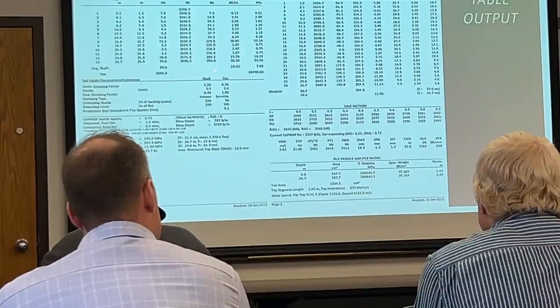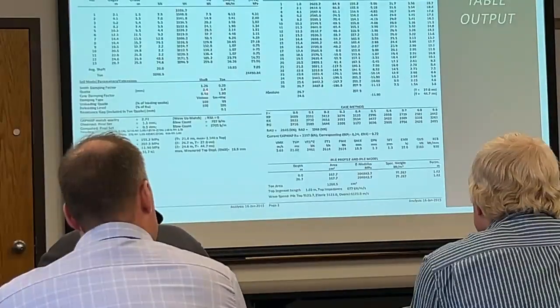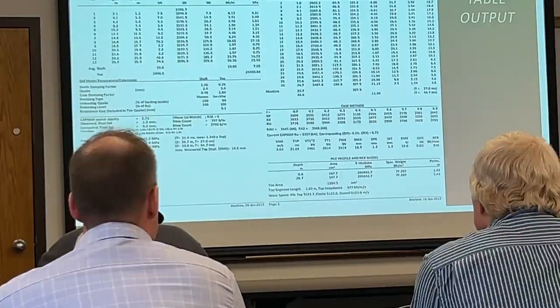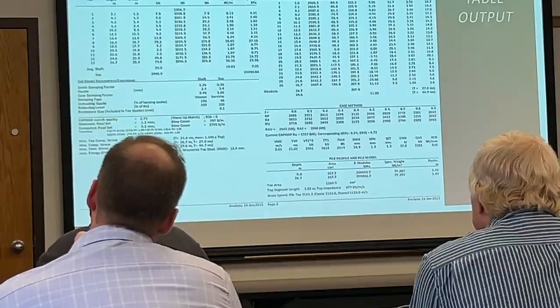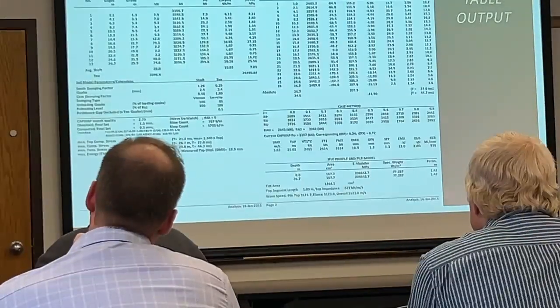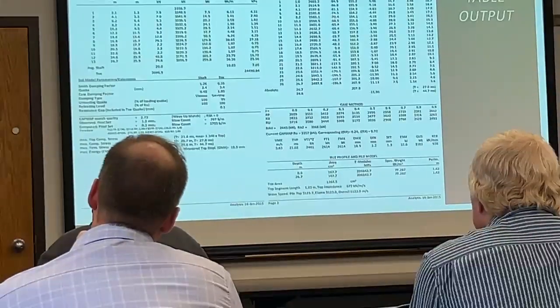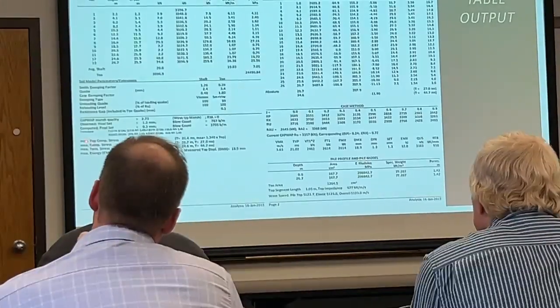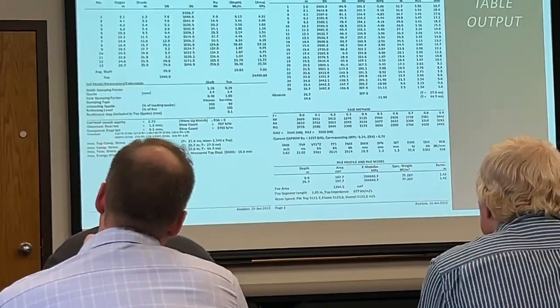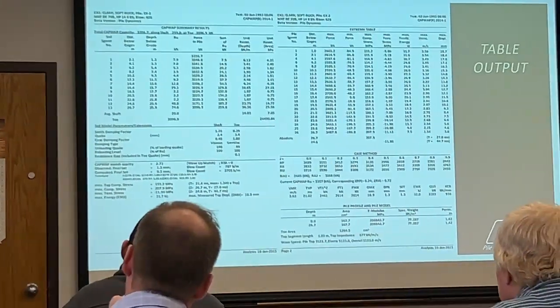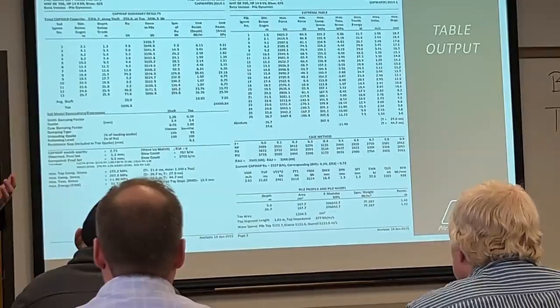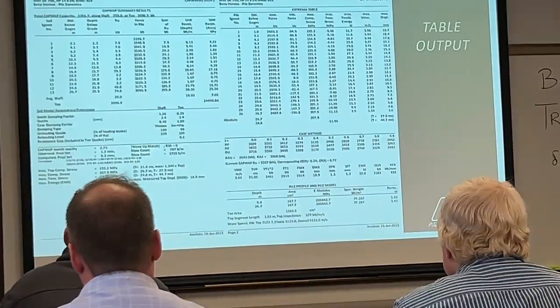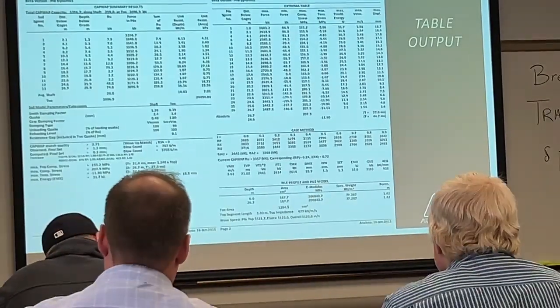The other factors in the model are here. Match quality is 2.7. We are comparing our computed and our observed sets. We also have indicators of the top stress and the compression stress, the maximas. The maximum top compression stress is something that we can compare to what we are measuring with our sensors in the PDA, because those are usually placed near the top.